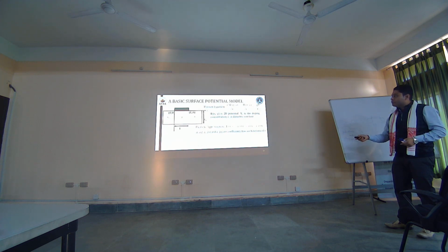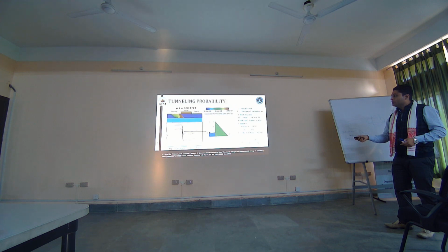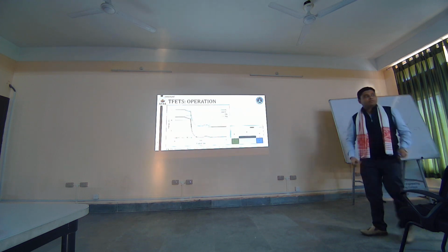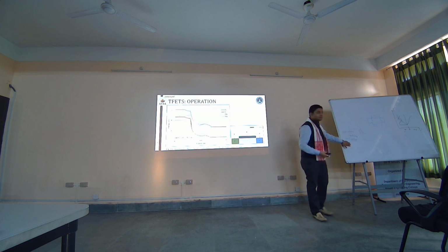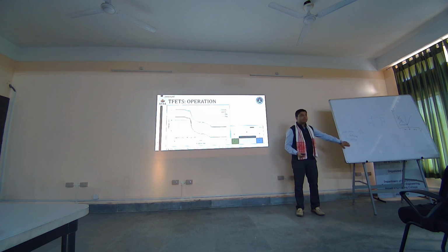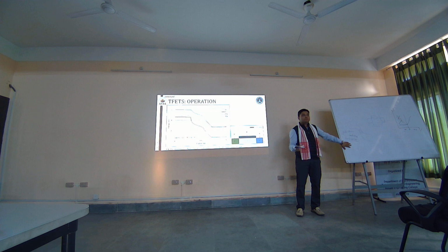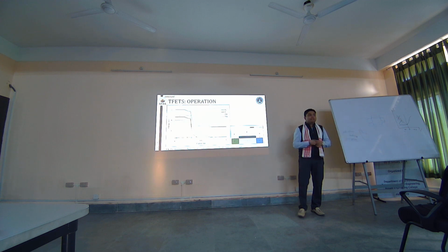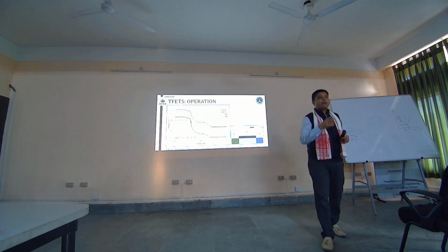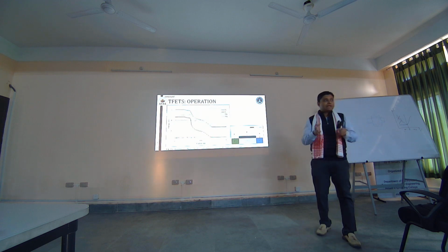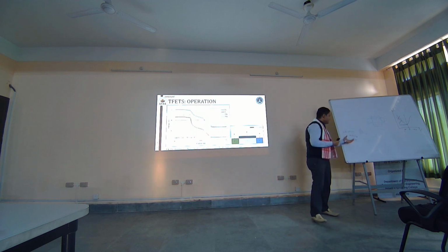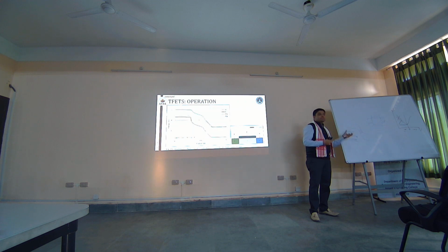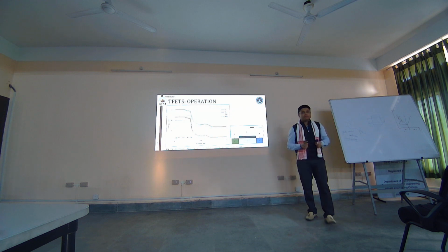Yeah. Let me go back to your ambipolar part, where we discussed that even in your positive and your negative bias, you can have appreciable current. We do not need the negative current, right? The current is in the negative bias. So we introduce this gate drain underlap. There is another way of reducing your ambipolar current, and sometimes this gate drain underlap is used simultaneously with that technique to reduce your ambipolar current in your tunnel field effect transistor.